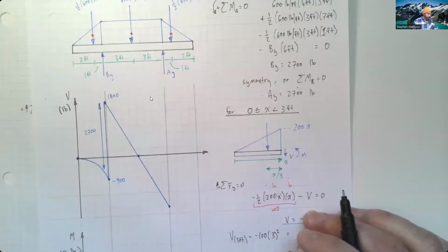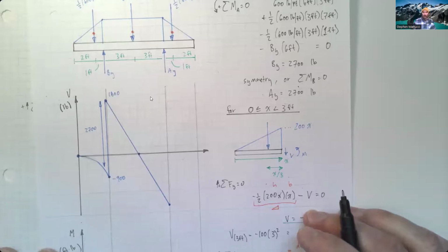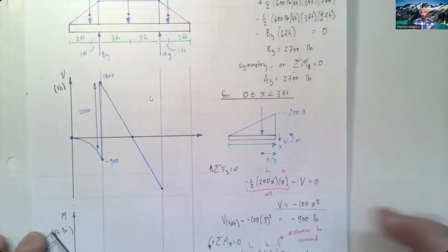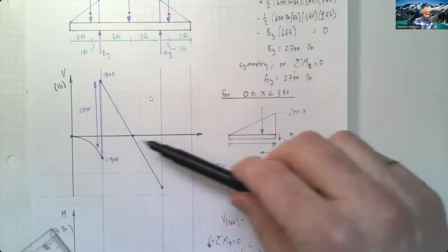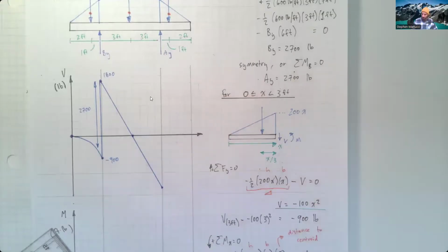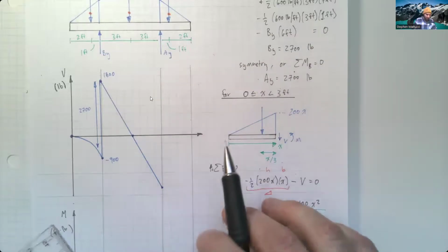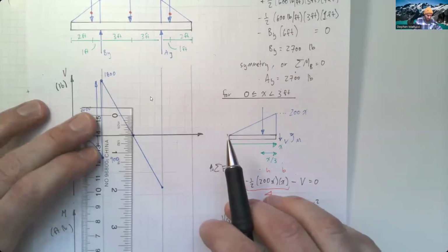And so it's going to look like this. Now, anytime you're drawing your shear and bending moment diagrams, as soon as your shear crosses zero, and this will be the case over here, we've already got the line there, but anytime your shear crosses zero, if this isn't a point of interest already, then we now need to make it a point of interest. So this is crossing zero right at the midpoint.